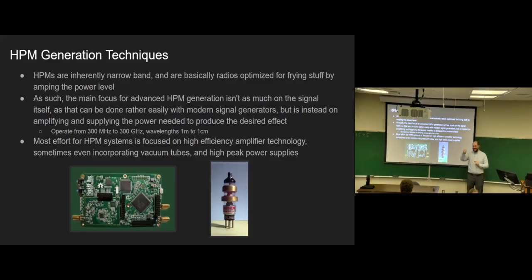When you oscillate as an RF wave, you're basically switching on and off really fast. Transistors are great when they're either on or off. But in the moment when they're swapping between on and off, they become a really bad resistor. And in that moment, they love to explode. So they're not quite there yet. The vacuum tube does not quite have that issue, so they still are vastly preferred for extremely high power applications.